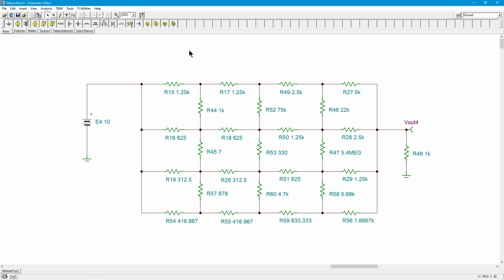If you think back about the original hint, the idea was, if I could say the voltages across the pair of resistors was the same, the end result would be we'd have a 0 differential voltage across one of those vertical resistors. So all I really have to do is make sure that the voltage across this sort of vertical ladder, these 4 rungs on this ladder, all get the same voltage. And the same thing would be true for these 4, and these 4 and these 4. But this voltage does not have to be the same as this voltage. And this voltage doesn't have to be the same as this voltage.